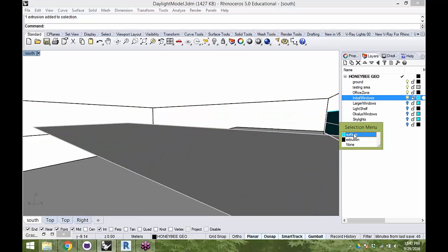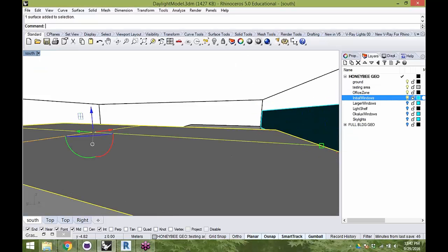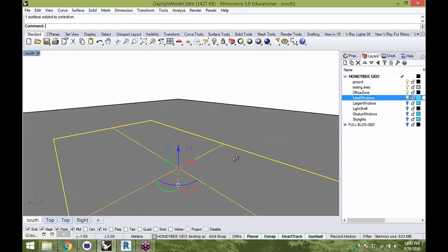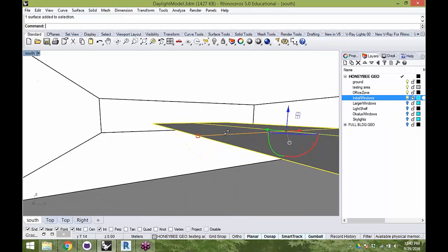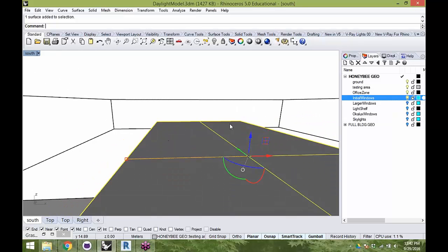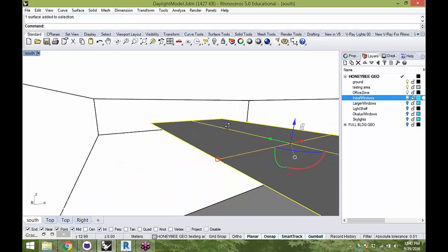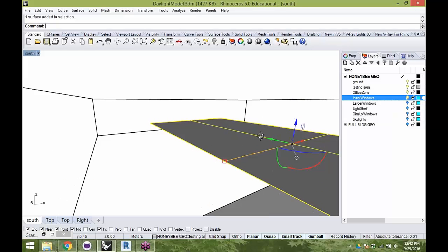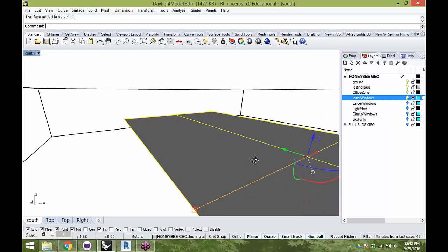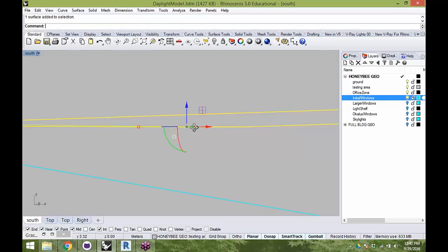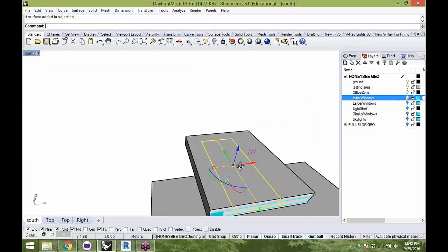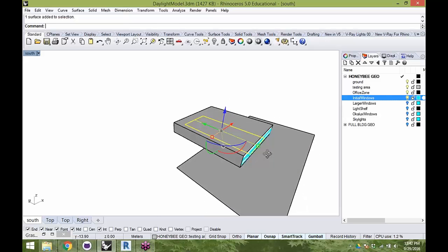We're going to evaluate a single window. We're going to extrapolate that up. And then we have a test surface here on the inside, which is essentially the area where we're going to evaluate daylight. And I've pulled it off a little bit from the side because we're imagining this is an open office plan, so we don't want too much light reflection from the side walls. That's why I've pulled it off the sides a little bit there.